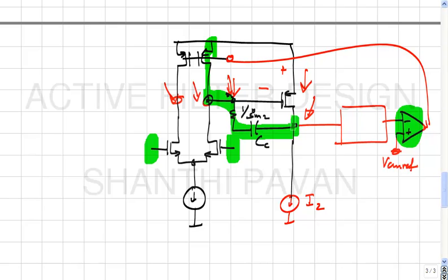What happens is that the output common mode, let us say, starts off at 0. The common mode feedback loop is telling you that the voltage is too low, it needs to be pushed up. If the output common mode voltage is 0, the only way to push it up is to yank the gates of the PMOS devices. Unfortunately, the input NMOS transistors are off.